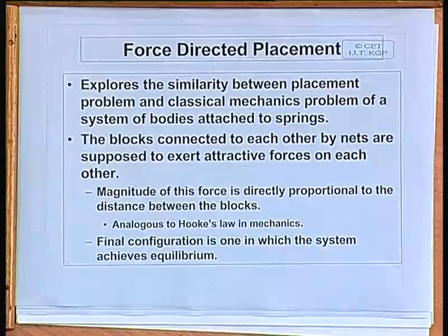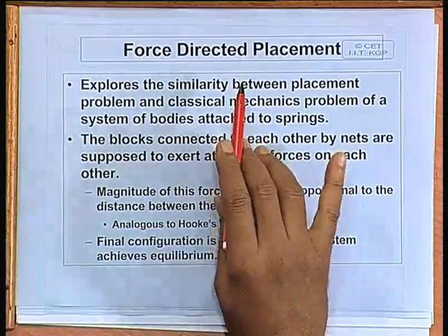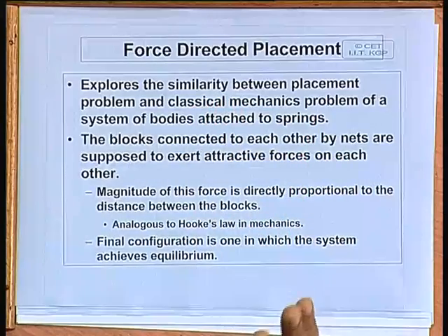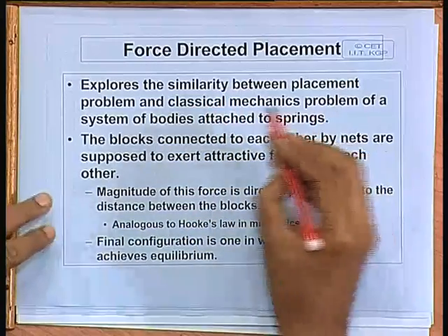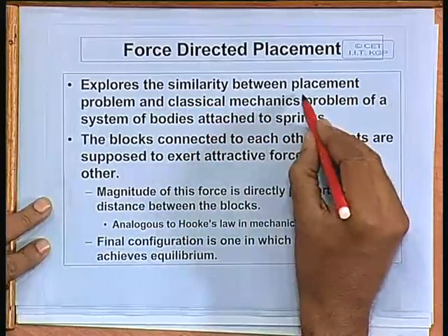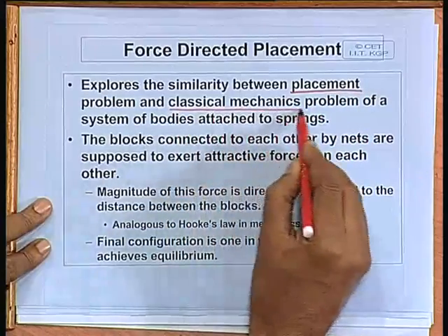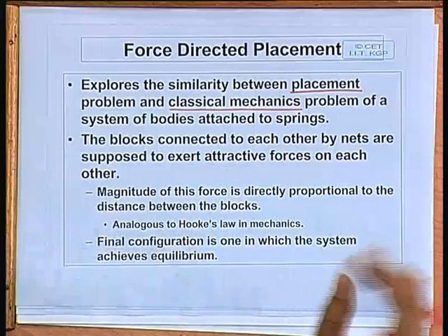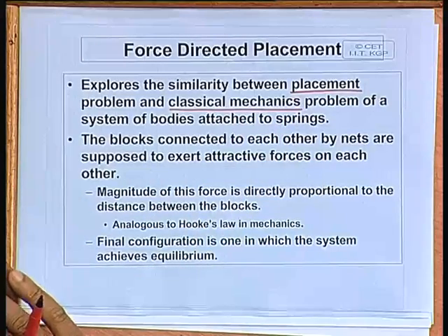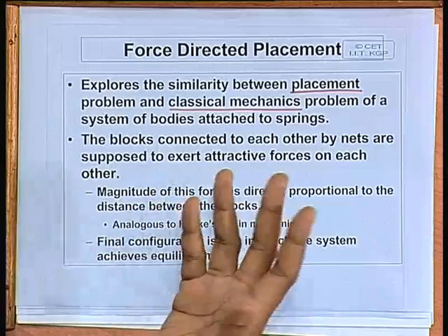The method is based on an analogy, a similarity between the placement problem and a problem of classical mechanics, a system of bodies which are connected by springs. In the placement problem, there are several blocks which are connected by wires. The more wires, the more the attractive force, so the placement algorithm will try to bring them together.